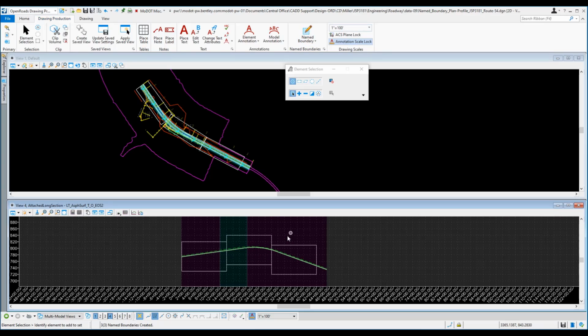Now you can adjust these vertically. You can move these just up and down. You can't move them left and right, or up station, down station. You can't move that. Right now, all that stuff with movement just really isn't working where we want it. You can move the plan shapes, and it'll recognize that. That's okay. But if you move a plan sheet, this one doesn't move with it. So you're really going to have to be careful on how you do that.